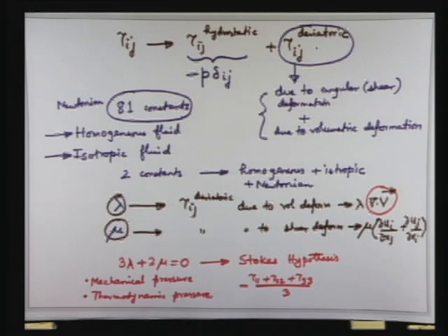So you have a mechanical pressure and you have a thermodynamic pressure, and in general they are different, because a molecule will have different degrees of freedom, translational, rotational, vibrational, and it takes time for all of these to be converted into a translational degree of freedom that is manifested in the form of mechanical pressure, which is the normal component of stress. This interconversion of degrees of freedom takes time.